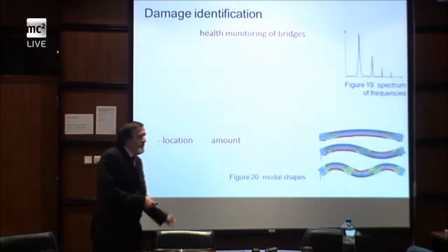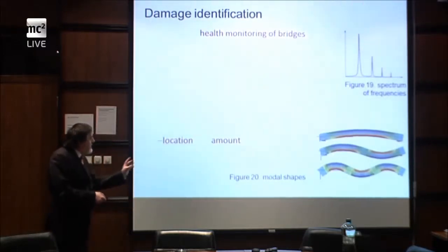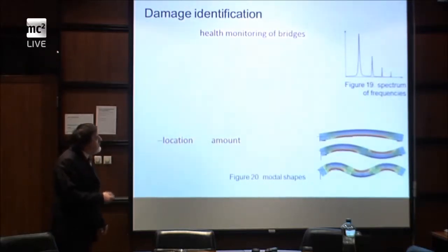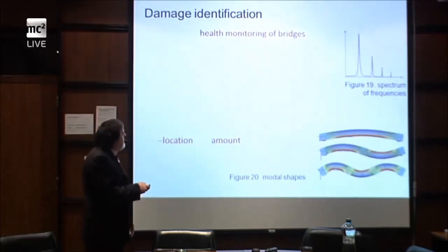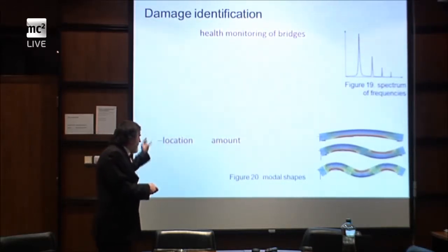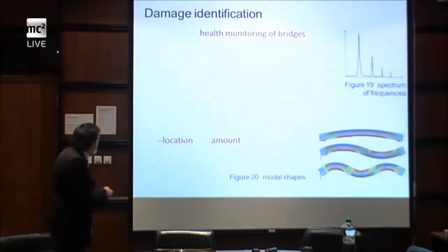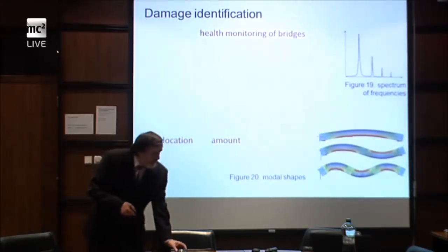So again, we virtually simulate the damage and parameters and observe the influence on eigenfrequencies or modes, and then we supply what is measured, eigenfrequencies and modes, and hopefully we can get the location and amount of the damage.